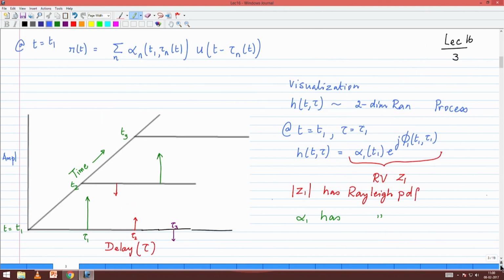One of the very useful ways of visualization of a multipath channel is to think of it in terms of 2 dimensions. One dimension being the delay dimension, the other one being the time dimension. So at any given point, if you take a snapshot, you get a certain multipath profile. Basically number of multipath components, the delays, the gains that are occurring. We have shown a few examples.